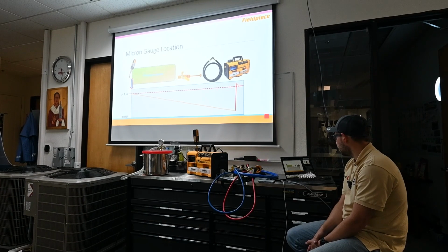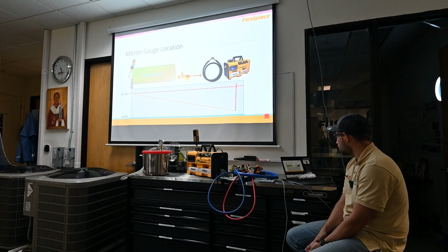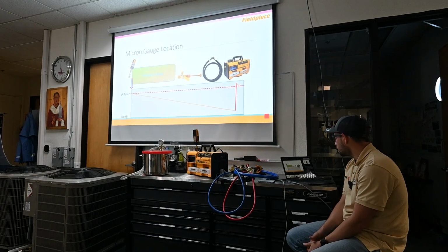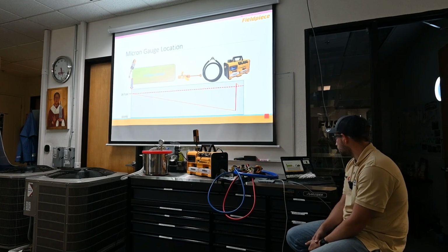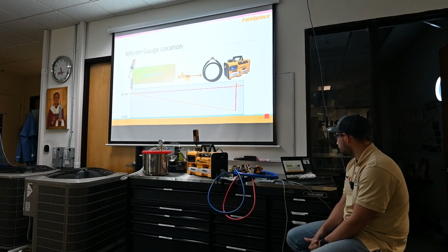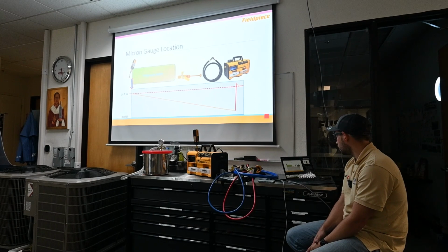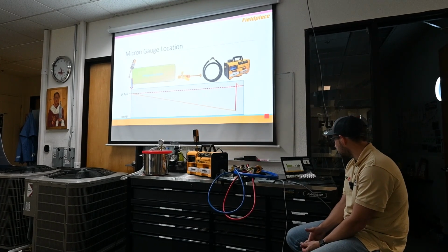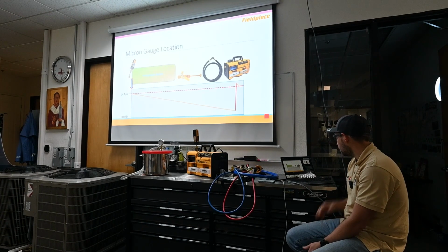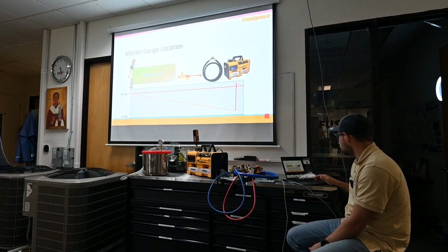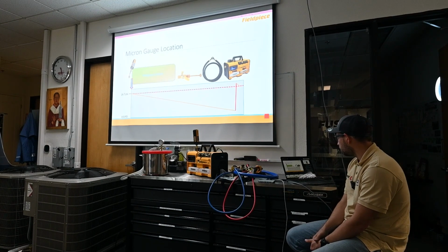An external stand-alone Micron gauge is preferable when compared to a Micron gauge in a manifold. Hoses and manifold can leak under vacuum. Small hoses and internal manifold passages reduce flow, which increases time. You need a minimum of 1 micron resolution below 1000 microns. You need a high accuracy gauge. You need to measure down to less than 100 microns.